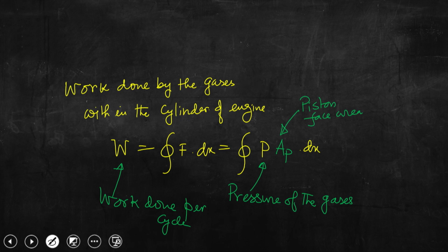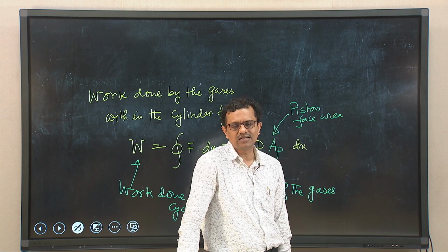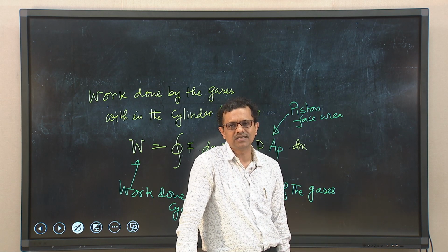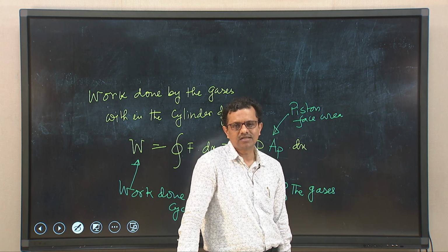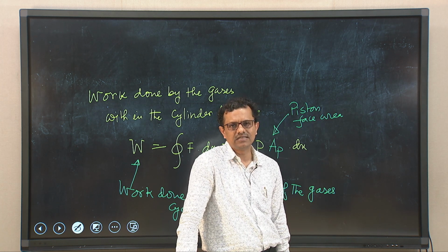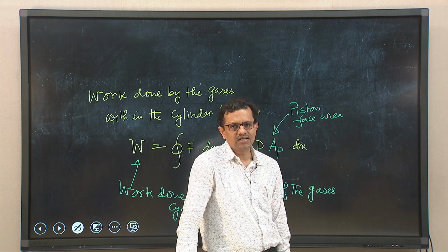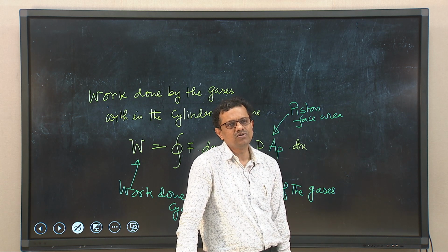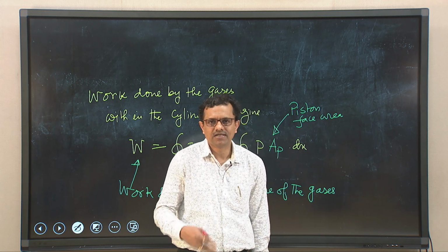The question is that, as I said, the pressure of the gases inside the cylinder changes continuously. It is not very easy to measure pressure variation. So, the target should be to measure the instantaneous variation of pressure in the engine cylinder. Nowadays sophisticated measuring devices are available with the help of electronics or digital technologies, but still the concept that was introduced was to use mean effective pressure.